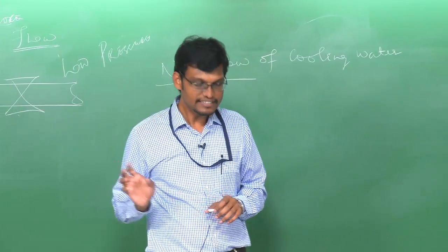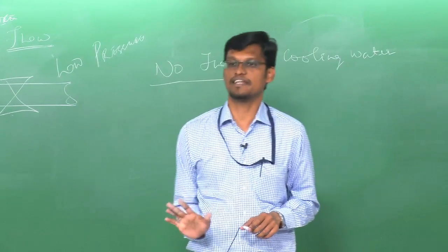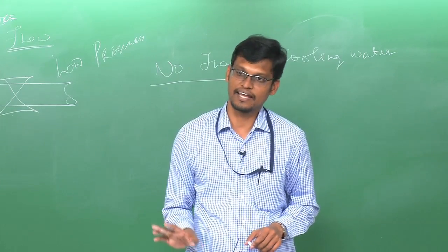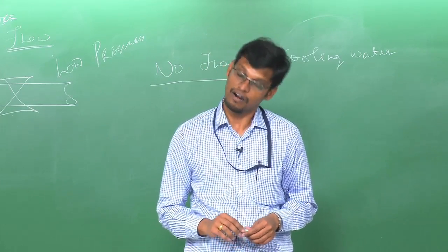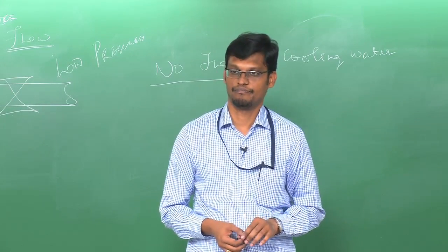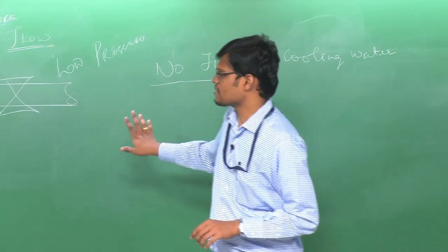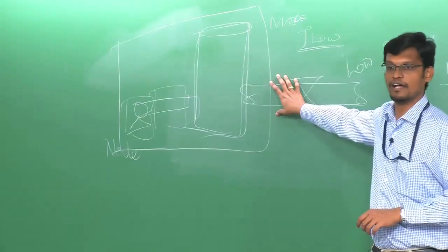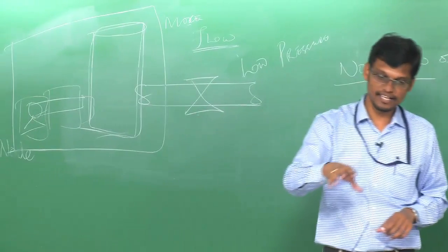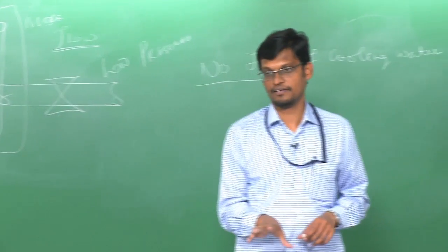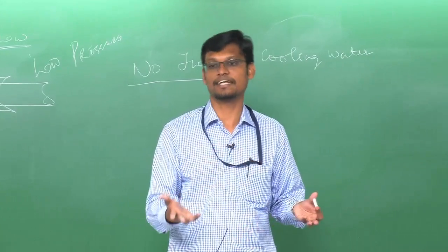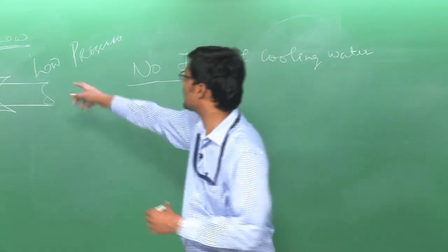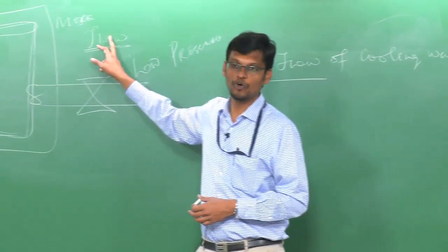And it is a very structured technique. There are standards available. There is a British standard on HAZOP. It's a fairly straightforward process. The only thing is you need to have a very thorough understanding of the process, and the team. As I say again, it's a facilitator-led study. So as a chairman, I will only lead the team, but the team has to come up with what will happen, how more flow or less flow can happen.